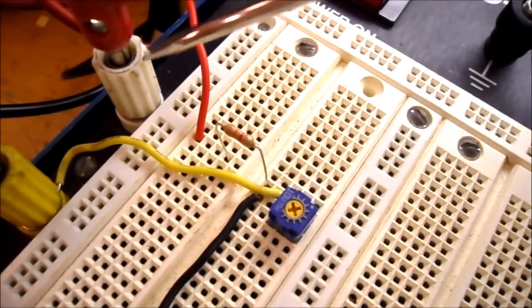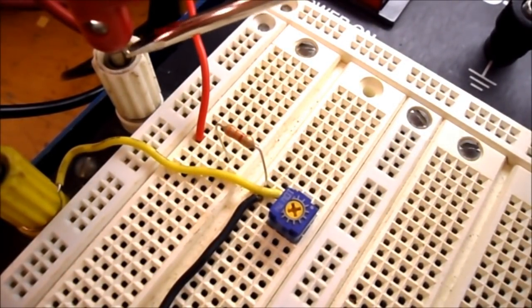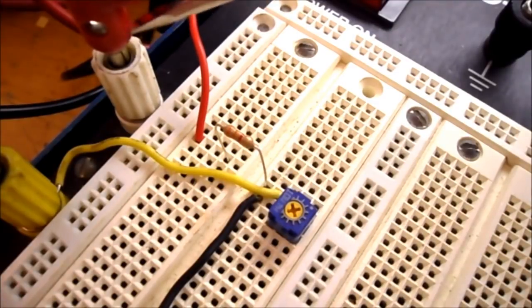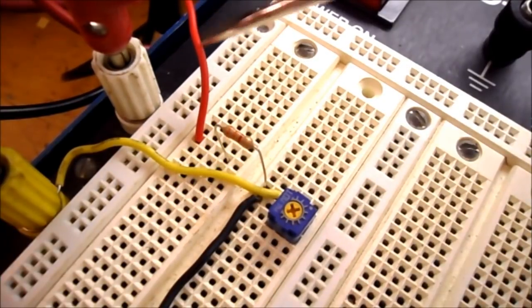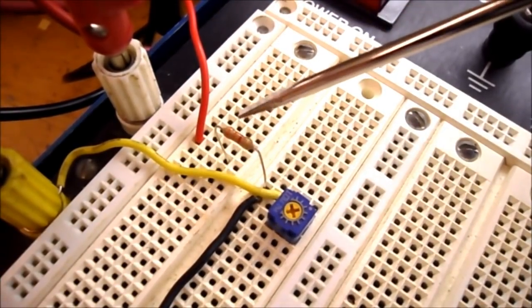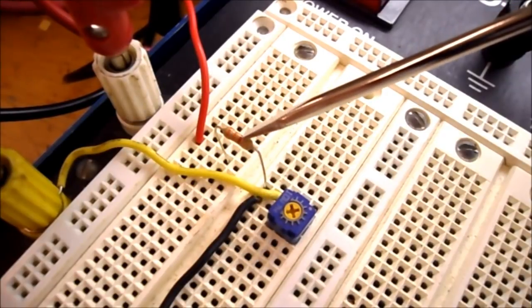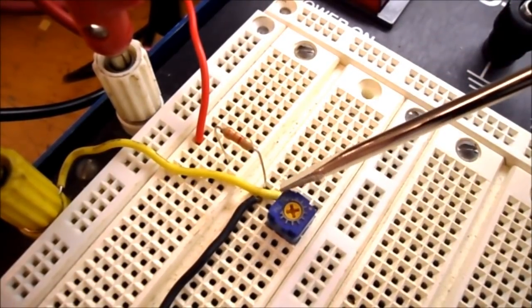So this is my circuit wired up on the trainer, and you can see the red terminal or the banana lead from the power supply, the plus 20 volt output, set to 10 volts, comes in and goes to my 3.3 k ohm resistor, which goes to the top of my potentiometer.